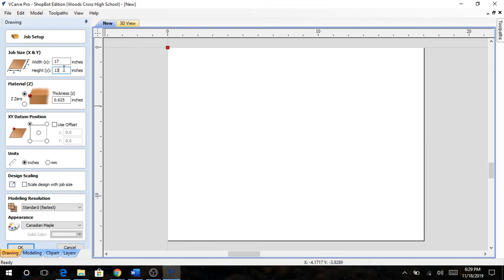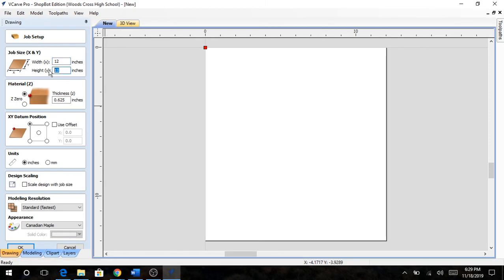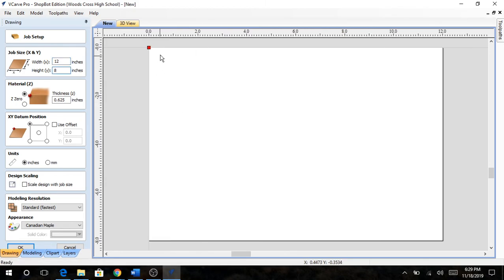And then with your sides, we're going to be cutting dovetails in on the ends, and they extend over 5/8 of an inch. So keep in mind that you don't have 5/8 of an inch here, and you don't have 5/8 of an inch here on your short and long sides. Okay, because that's going to be cut out with the dovetail. If you engrave over in there, we're going to be cutting it out anyways. So leave a little bit of space on these outside edges.